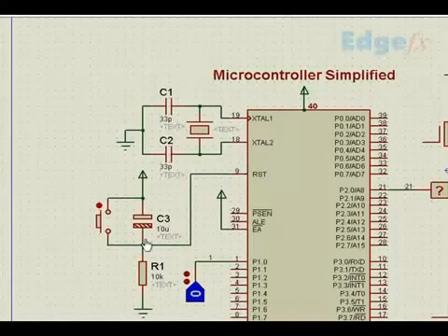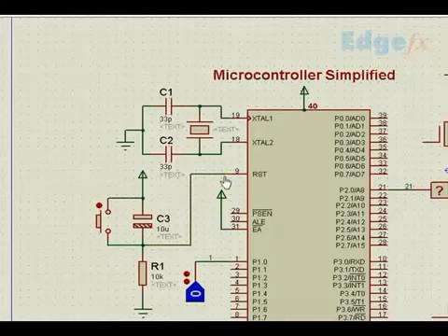After some time, when the capacitor stops charging, this point goes to low. That means initially this point will go to high, and after some time it will go to low. You know what that time is? The time is very small, of the order of the time constant of RC. It could be some milliseconds or even microseconds, and you will not even notice that.